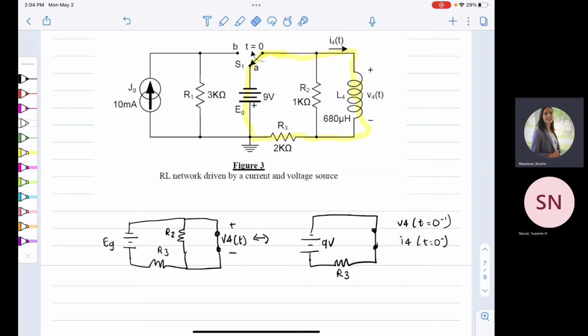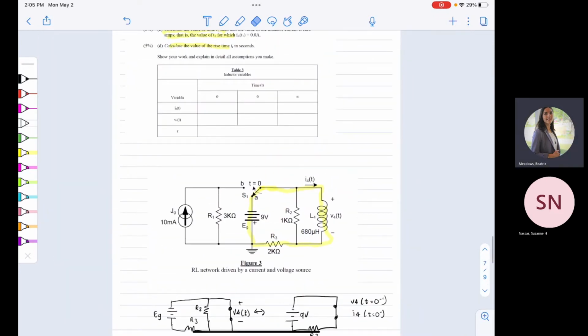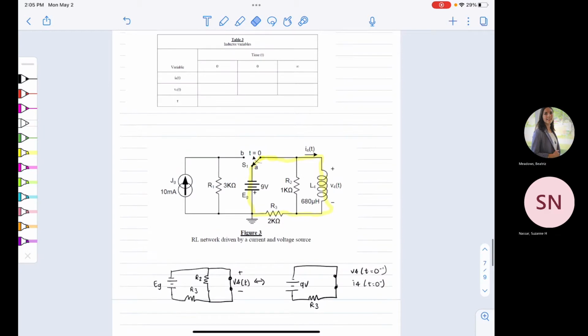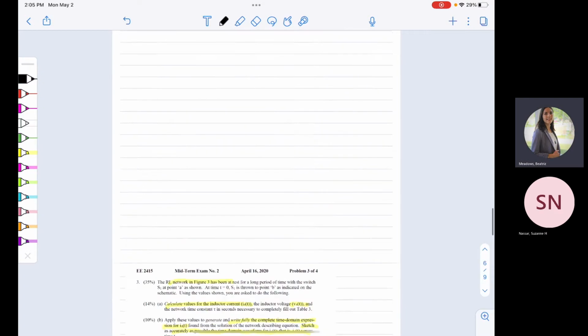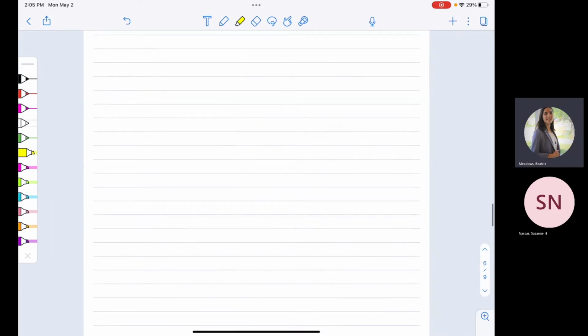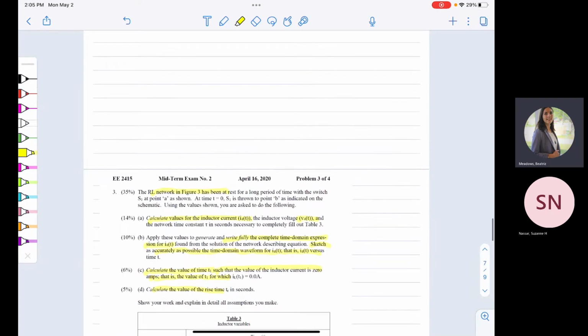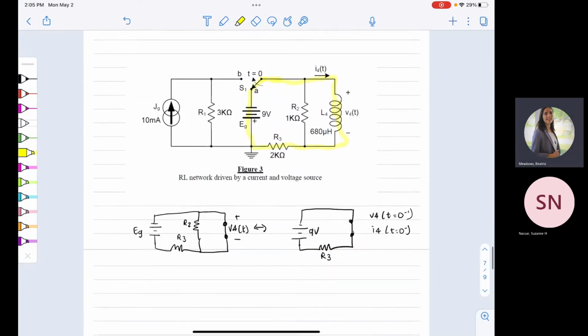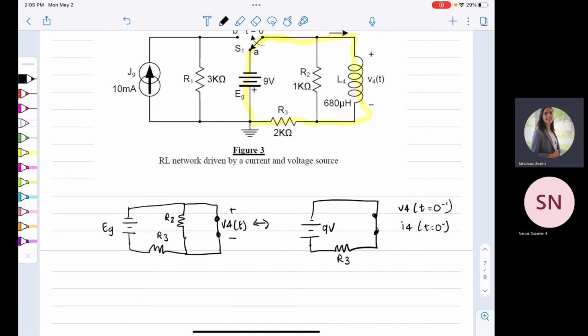Okay, perfect. So remember I told you in this table there are going to be two values easy to fill out, and that's the voltage through a short and the current through an open, okay? So on both of your tables, now we have a 0 here. And remember on Suzanne's problem, she had a 0 here. So right off the bat, you can get like 5 points just by knowing where to place the 0. That's some freebies. Okay. So what will be the current through this branch?